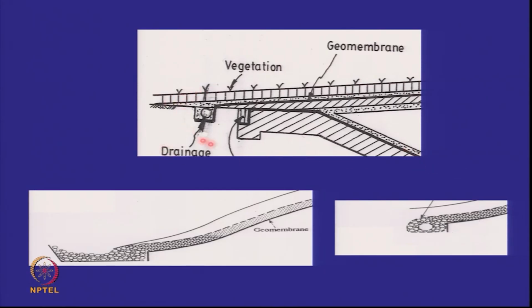So you can have several arrangements. You can have an arrangement like this, which is the same thing here, or you can have a trench made of cobbles and the water can be taken out in the storm water drainage system. So this is important. In some of the landfills, this detailing is not done properly. You know what happens? This becomes connected with this. This is a very small distance. If you leave this somewhere here, it will sort of reverse flow into this.